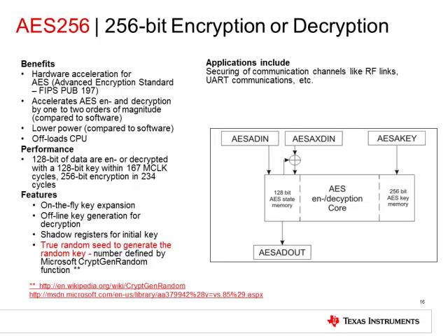The AES accelerator module provides automatic clock activation for MCLK for use with low-power modes. When the AES accelerator is busy, it automatically activates MCLK regardless of the control bit settings of the clock source. The clock remains active until the AES accelerator completes its operation.